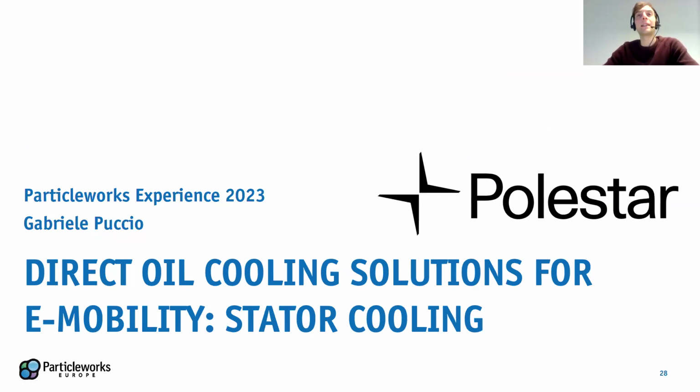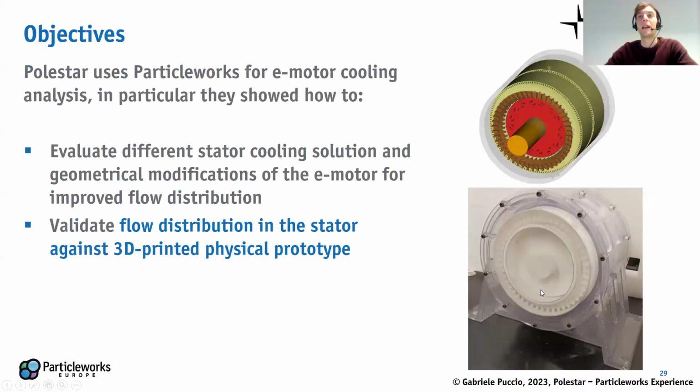Another example was discussed at our conference, Particleworks Experience, in 2023 by Gabriele Puccia at Polestar. In this case, there were several validations. One validation was on oil flow visualization using a clear casing 3D printed prototype. Here you see the prototype and the model investigated by Polestar, and I want to highlight that we have an injection point on top of the stator. Oil is injected here, can flow through the stator and then spills down to the windings.